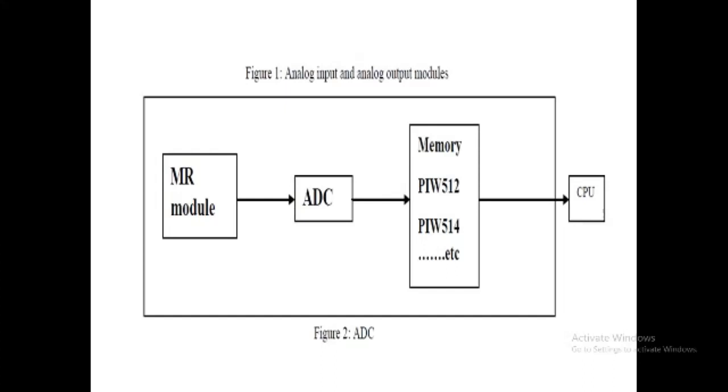In the ladder logic program, FC105 reads the integer value of the analog input stored in PIW 512.